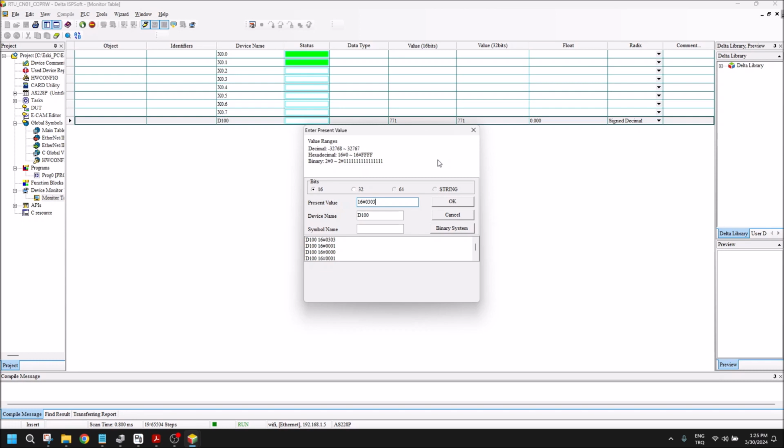It will activate 2 of my outputs. Let's put here 0F0F. It means 4 of my outputs will be activated, and the FF will be activated all my outputs. So you can use these 2 methods for communicate RTU-CN01 remote I/O connection module